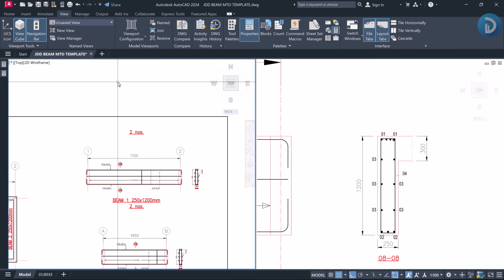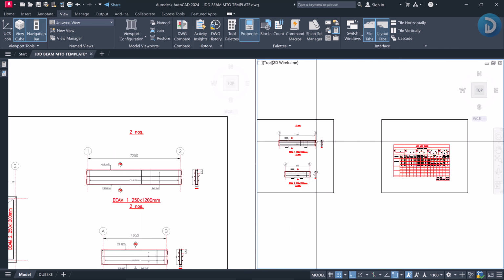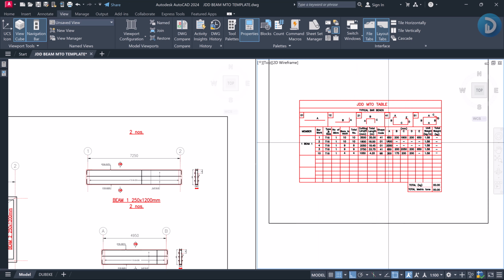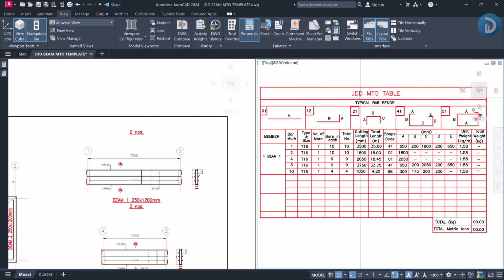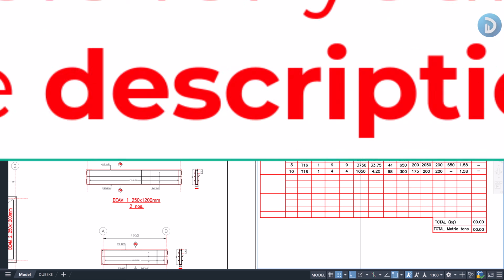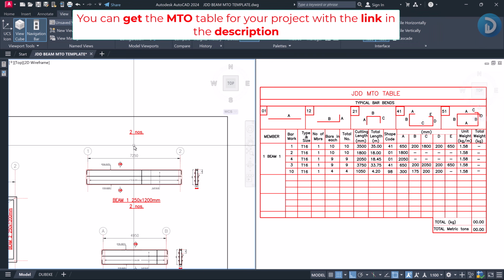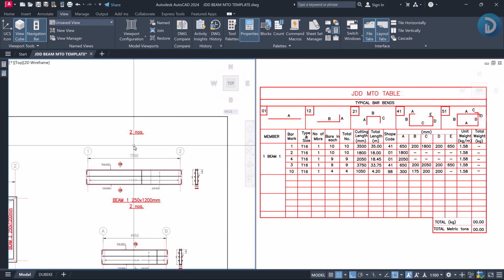In order to get the different properties which we will input in this table to help us calculate the total tonnage required, the next thing you need to identify is the various shape codes of these different reinforcements that you've identified. And this shape code is not something you have to develop yourself. It is universal, so long as you are designing or detailing with a code of practice. It is given by your code of practice.